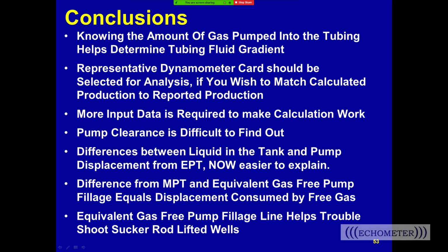Well, putting aside that low probability option, we have a shallow well with a big plunger, so we have fluid inertia involved in there. And the second option that you mentioned was having a wrong input on the sucker rod string. And I could have a third one that is not necessarily for heavy oil, but also some hydraulic pumping units that are not in good balance can create really wavy upstroke and downstroke dyno cards.